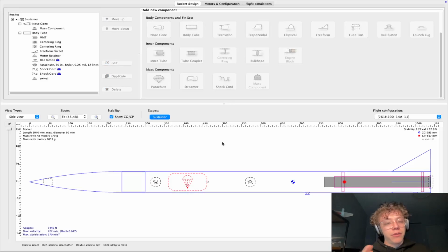So if you're flying above like 3,500, which I'm basically there, have a chat with us and we'll see if we can incorporate an altimeter in your rocket. And then, sorry, a GPS in your rocket, because you're going to need to track your rocket when it comes down, because you're going to be going pretty high up and you probably won't have eye connection the whole time. But if I was a little bit afraid of this, I could maybe add another layer of fiberglass or make it a bit longer. There's a bunch of different ways to go around not going as high, or make my fin smaller, make more ballast so it's heavier. There's many ways to do that. So yeah, I think that's it there.